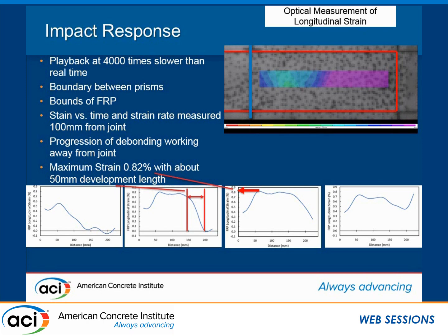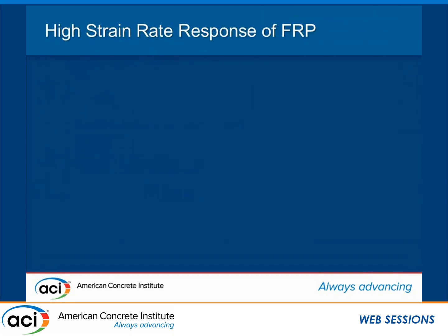This implies to me that there is potentially, and I'm going to really guard my words here, one test is even fewer than the two that we were drawing conclusions from before. This is ongoing research, and I've got 50 of these things to do. All I'm showing here is one, so it's too early to draw conclusions. But based on all the static tests, the worst I ever saw was a strain up to 0.7. In here we get a strain of 0.82%.